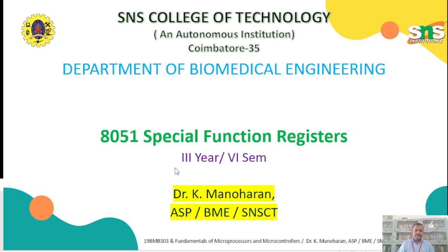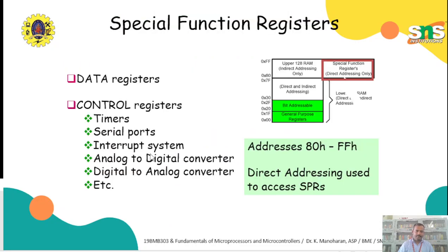So today in class we are going to discuss the 8051 SFR registers, that is, special function registers. Look at this. Actually, this is the internal RAM. Inside this is the special function register. This is from 80 to FF. This will be mapped with the locations.